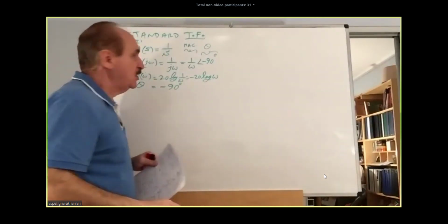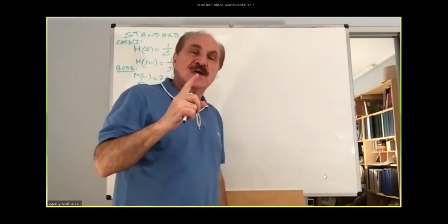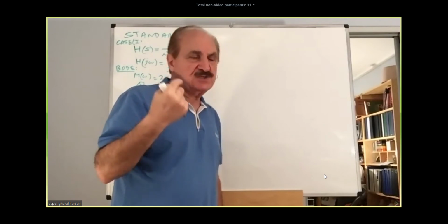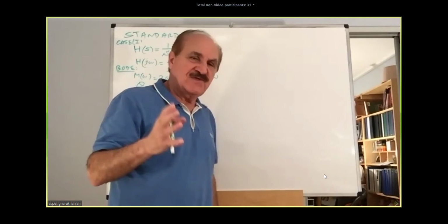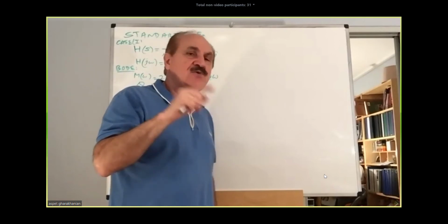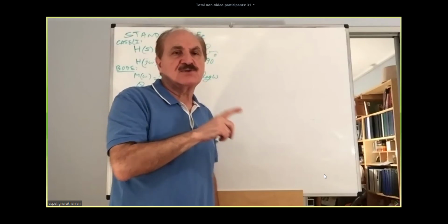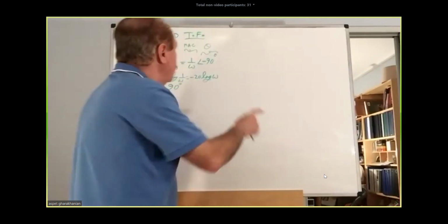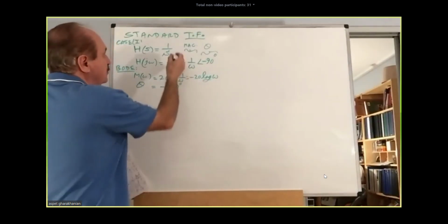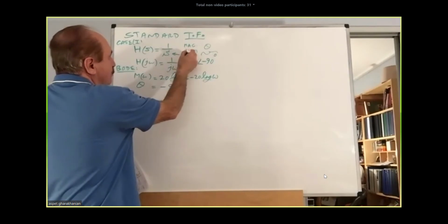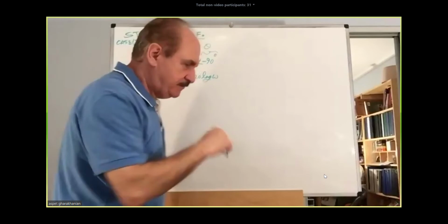A transfer function of 1 over s is referred to as a single pole transfer function, with the pole being at the origin. Remember the definition of the pole: the value of s that turns the transfer function to infinity is called a pole. In other words, you find the poles by setting the denominator equal to 0. This is the denominator of s, and it has just one term.